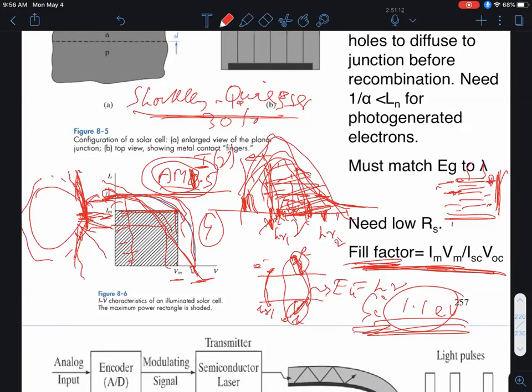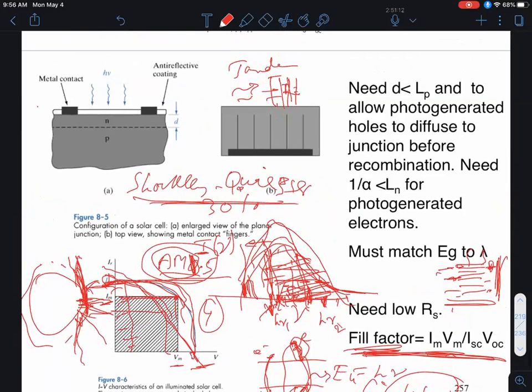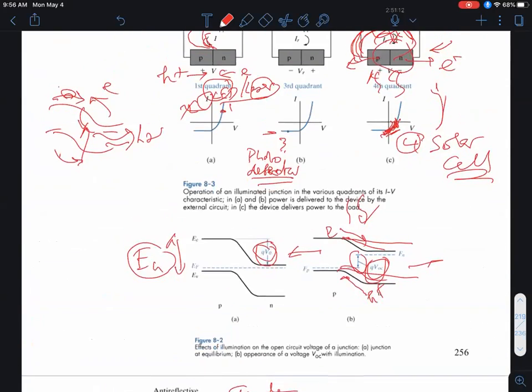Now, without going into the details, one can show that the lower the series resistance, internal series resistance, RS, of my solar cell, the more box-like the IV would be. The higher the value of the series resistance, more like this, the IV becomes, okay? And in fact, it's very similar to the issue that you have in a regular battery also, okay?